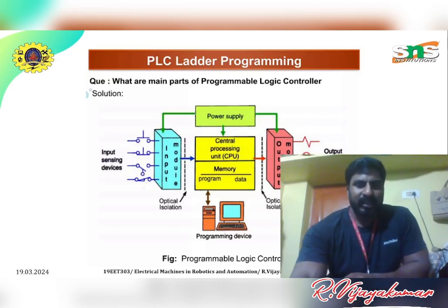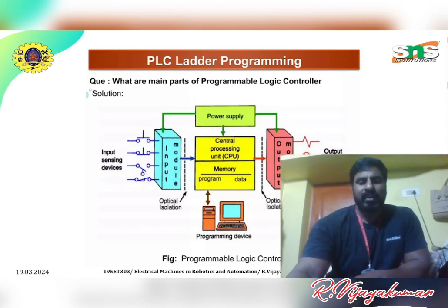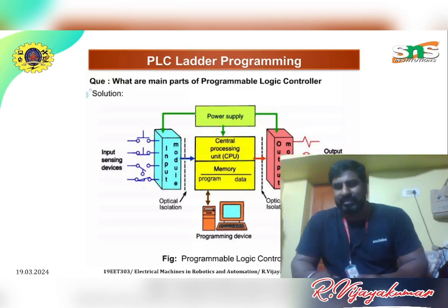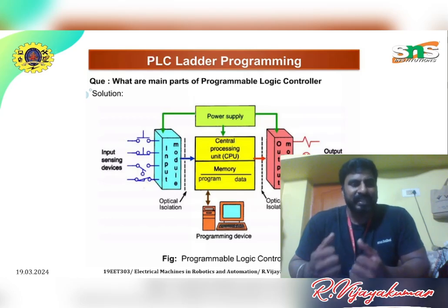Ladder diagram is one of the important PLC languages, along with structured text and function block diagrams. In a ladder logic diagram for a programmable logic controller, we have input sensing devices and output load devices. The input sensing devices may be switches, sensors or relays, whatever it may be. They sense whether the signal is high or low, that kind of digital signal.